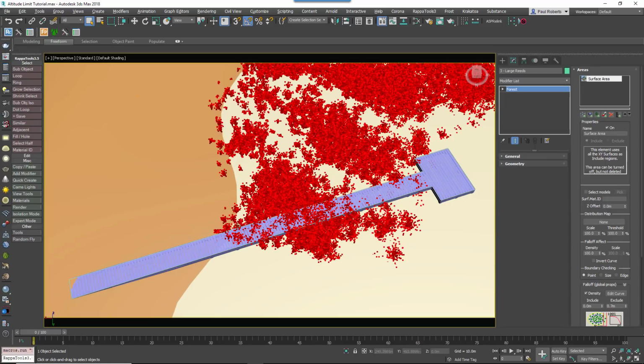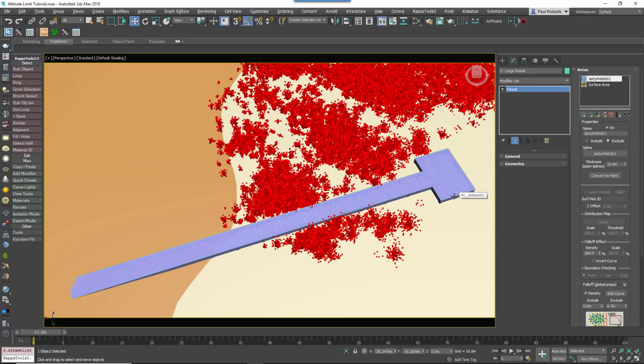You also need to remove the reeds from the jetties. Fortunately, these are rail clone objects and they already use a spline to define the footprint. All you need to do therefore is to add them as exclude objects to any of the affected scatters, mainly the reeds.